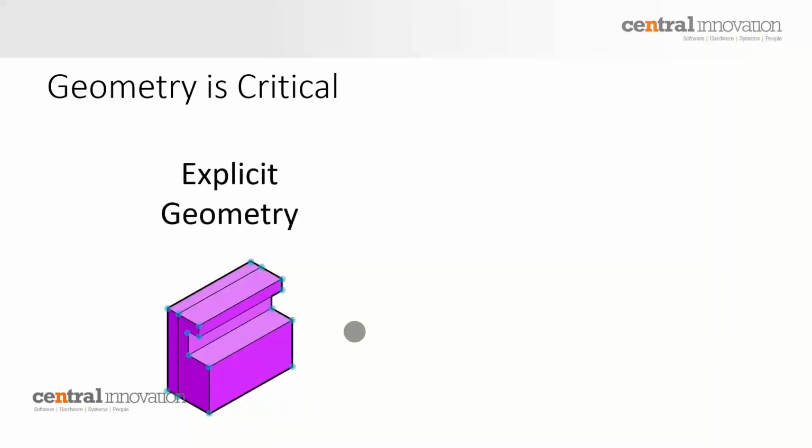Now, there are two ways for computer software, and for IFC and all BIM certified software, in a sense, to read and write geometry, in essence, to understand geometry. There is explicit geometry, and that is the typical case for boundary representations, but also a triangulated surface like a mesh. In that case, the computer will actually be describing every individual point, corner, edge, and face of the geometry in order to build a volume or a solid.